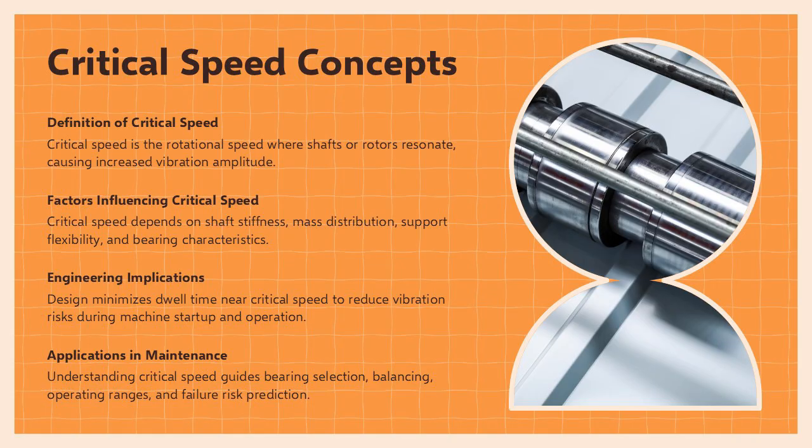The content explains that many machines must pass through critical speed during startup, necessitating careful engineering design to minimize dwell time in this dangerous region. Understanding critical speed allows engineers to appropriately select bearings, set machine operating ranges, conduct balancing activities, and predict failure risks. This foundational knowledge supports later discussions on vibration testing and corrective structural modifications.